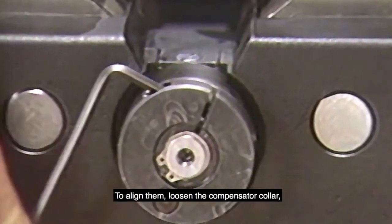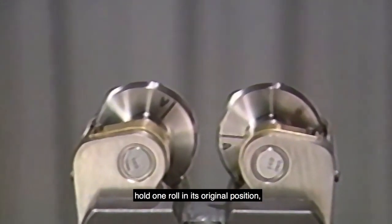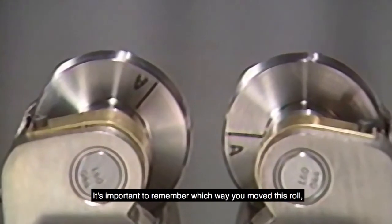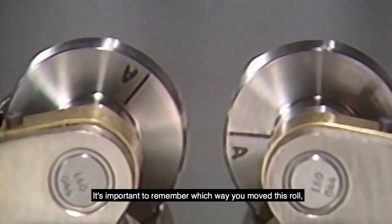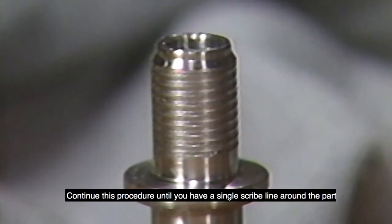To align them, loosen the compensator collar. Hold one roll in its original position and move the other roll either up or down slightly. It's important to remember which way you move this roll in case you go the wrong way and make the condition worse. Continue this procedure until you have a single scribe line around the part.